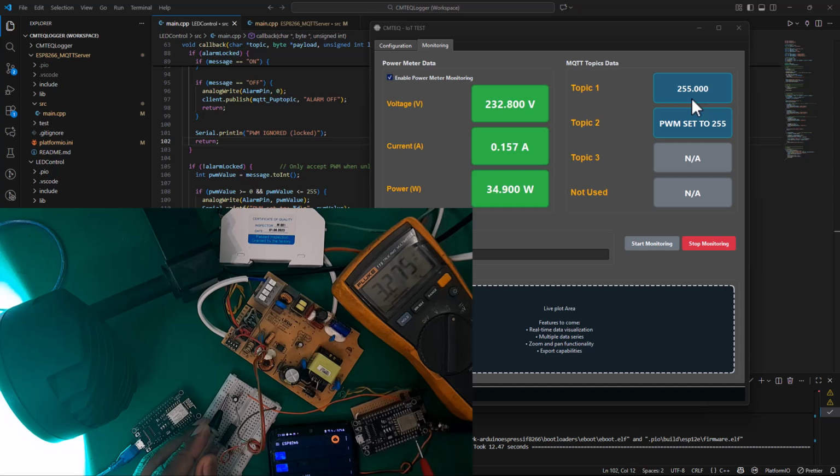You can see here, this is D1, the pin that I'm actually controlling. The PWM is sitting at 3.2 volt. Here at the input, it's also 3.2, but the RC filter output is only 2.8. So for some reason, I'm dropping some voltage across this 10K resistor. So I probably need to increase that value so that I can minimize the drop there.